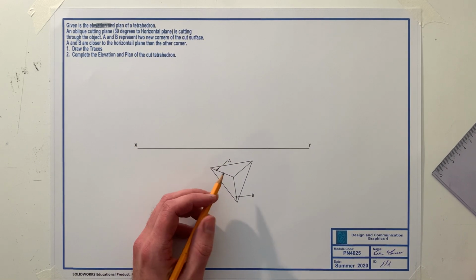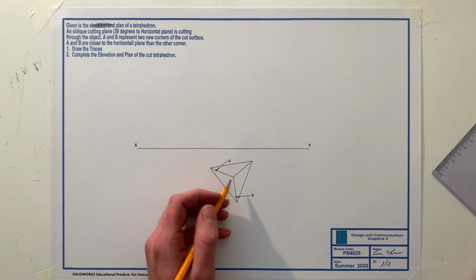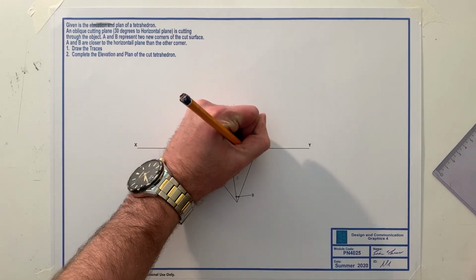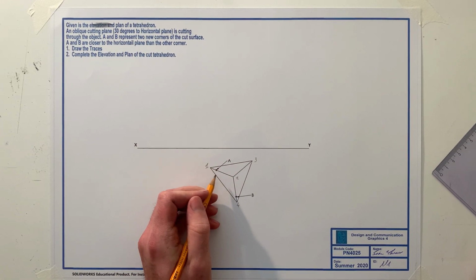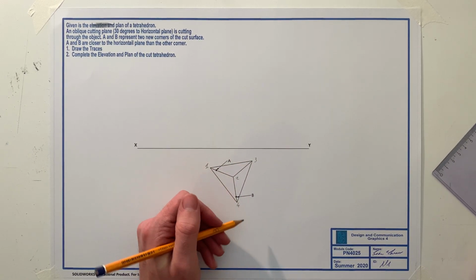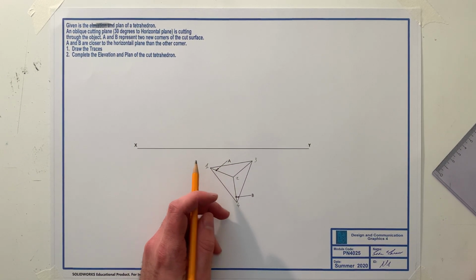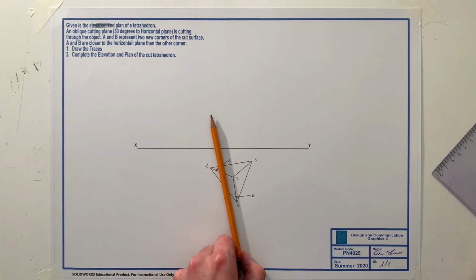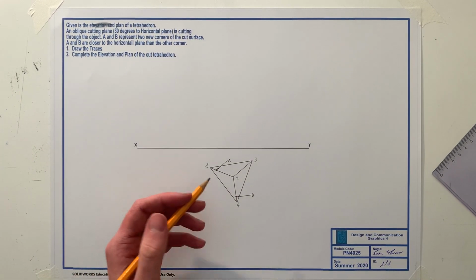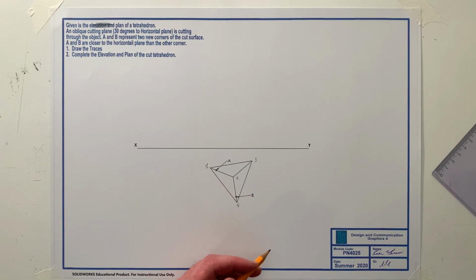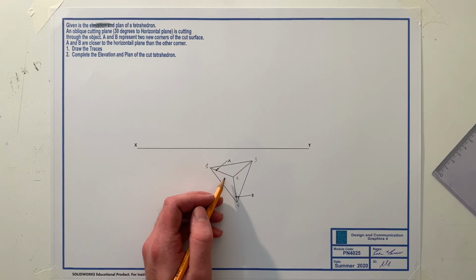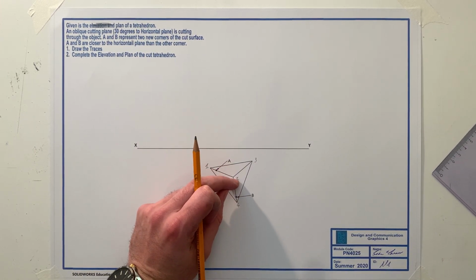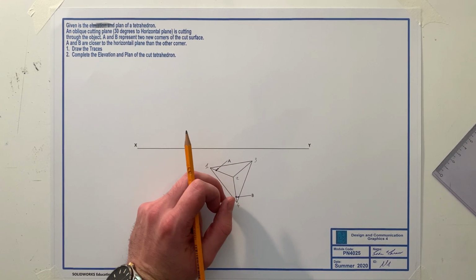So to do that, what we need to do is take an auxiliary view of this. Now the auxiliary view we're going to take is going to be parallel to one of the lines here, which I'm just going to call 1, 2, 3 and 4. So it can either be parallel to 1 to 2, the line 3 to 2, or 4 to 2. If we have an auxiliary view that's parallel to any one of these, like so, what we can do from that is get an auxiliary elevation, and from that auxiliary elevation we can use the line that we've taken parallel to. We can now take that as a true length and then find our location, or basically the height of 2 from the horizontal plane. Okay, so I'm going to do that now.